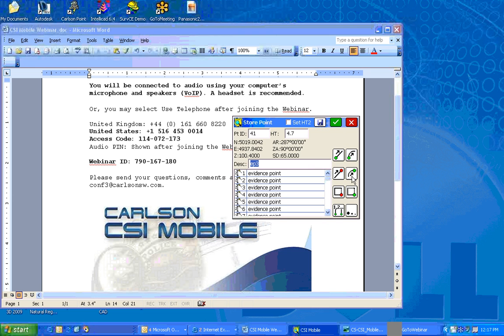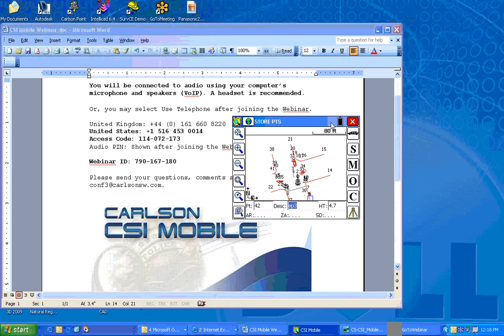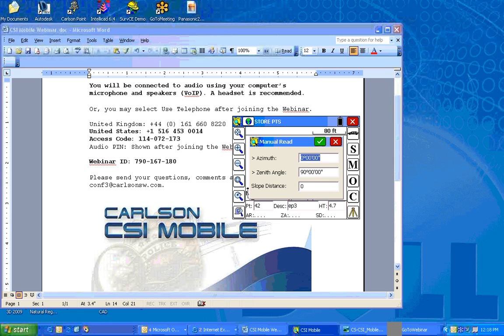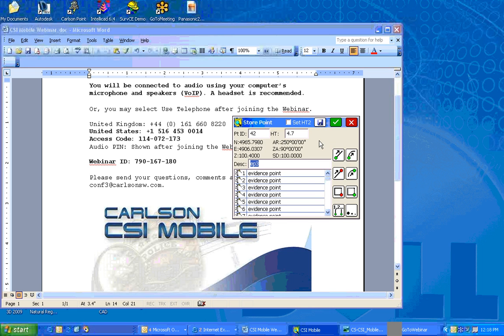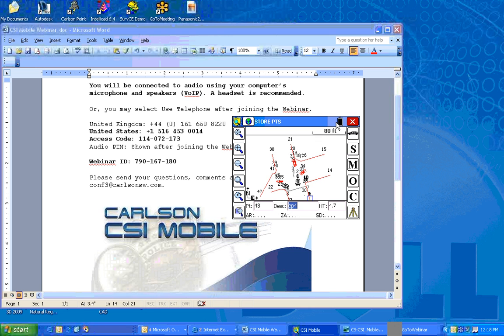You don't have to end the curve, because if you just do 2 additional points, it assumes a 3-point arc. So I've hooked that arc pretty tightly there, and then you would take another shot to continue it, and I'll just attempt to do that for you, to end the line. So we hit enter, and maybe I'll go 250, and push it out there 100 feet and see where we end up. And we'll call this the end line. That's the end line icon. Well, I kind of ran it off to the side.